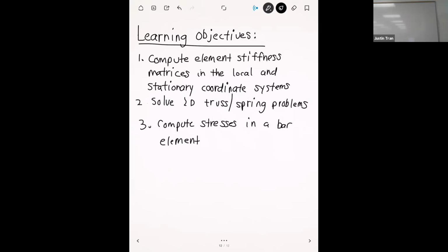So it's only doing it for the road, because normally you click on the equivalent stress right here. This does it for all bodies, and so I think you might have had those two selected when you created that total deformation. And so, I actually don't know how to change it from here. Usually what I do is I just delete it.